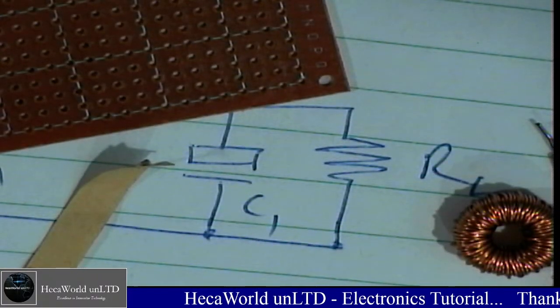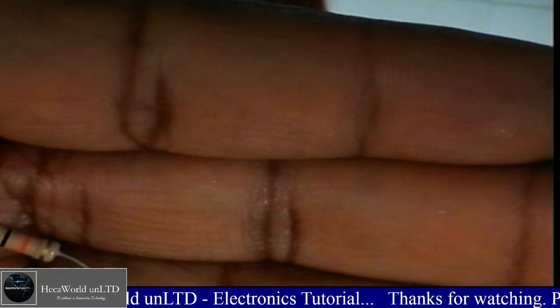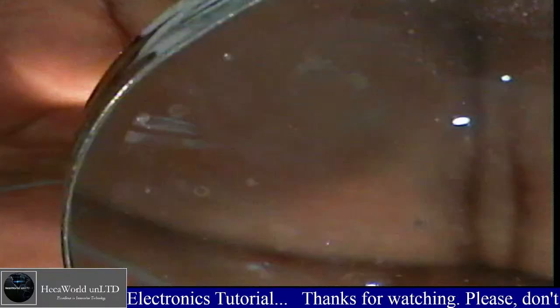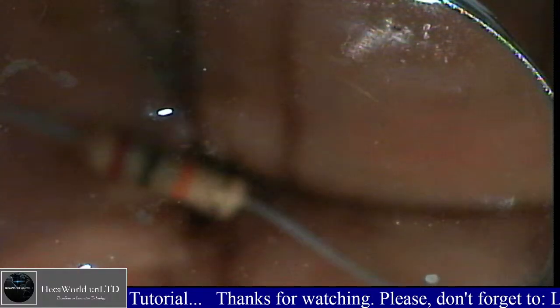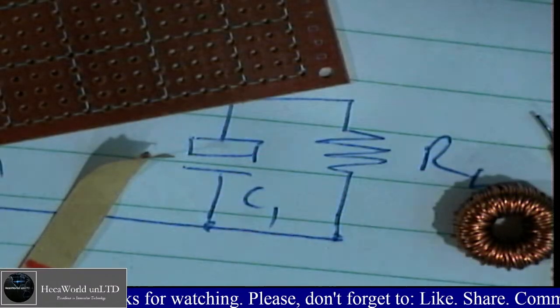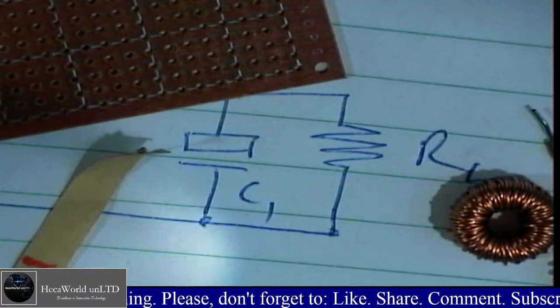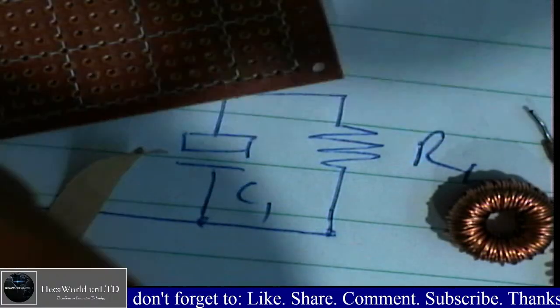Let's see if we can magnify it a little bit, if it helps. Yeah, you can see it. It's red, black, orange. Red is 2, black is 0, orange in the third band is 3 zeros, or times 10 raised to the power 3.